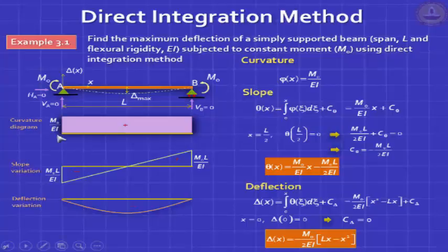Remember that when the loading was uniformly distributed in a symmetrically supported beam, the shear force diagram changed linearly and the bending moment diagram changed quadratically. Except that there, the normal gravity loading is negative and this got flipped over and this became positive. Now it's the other way. Right. And you can also substitute values to find the maximum deflection.